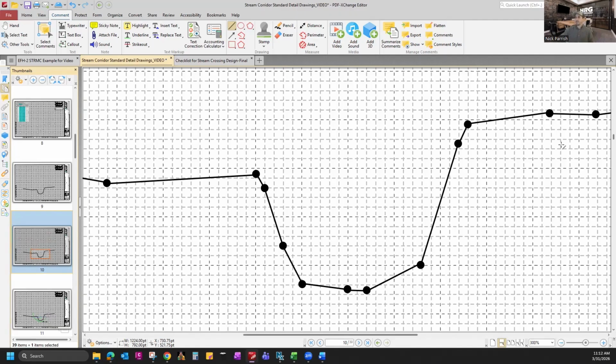Now, to do that, there's two main things to consider, one of which being our slope should not exceed 6-1. 5-1 is still okay depending on the type of crossing. However, the flatter the better, just for animal safety, walking up those slats or gravel and being able to get their footing without slipping and injuring themselves.